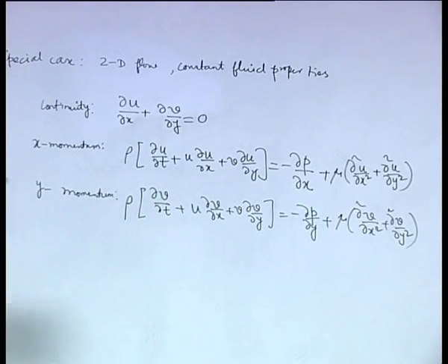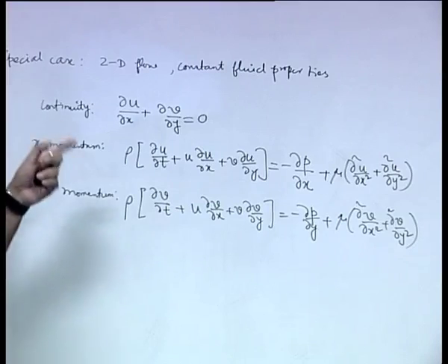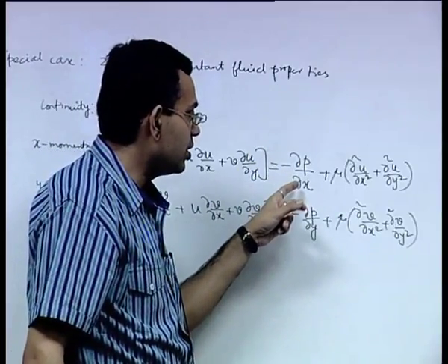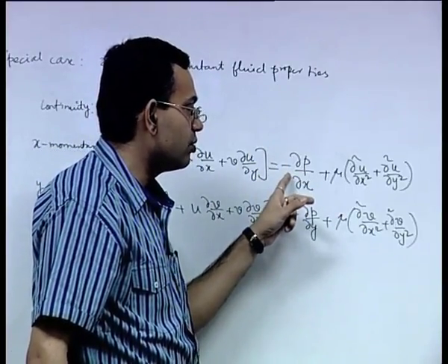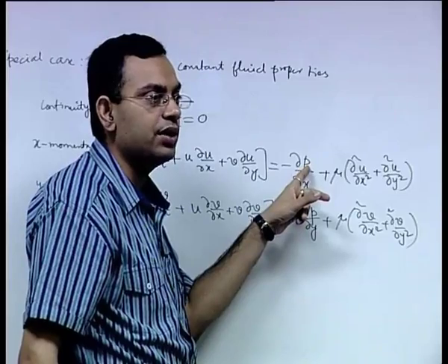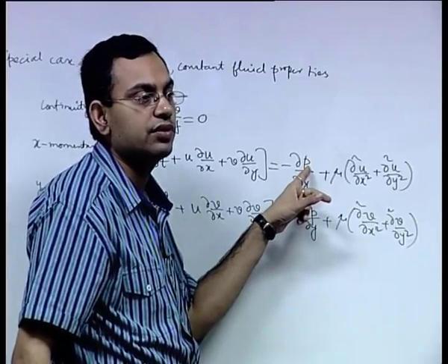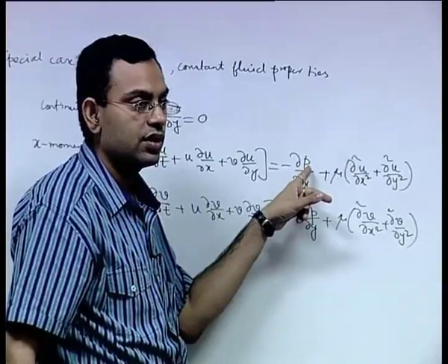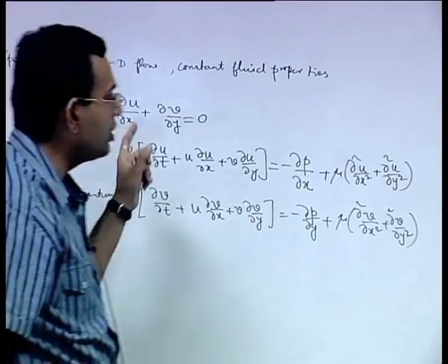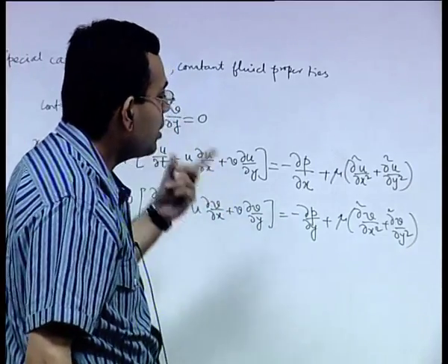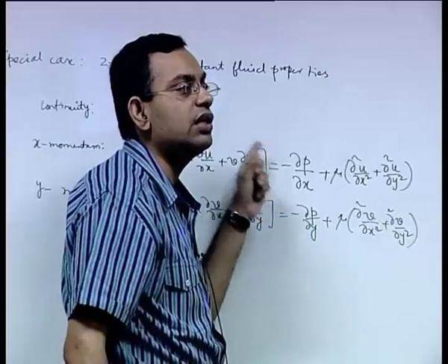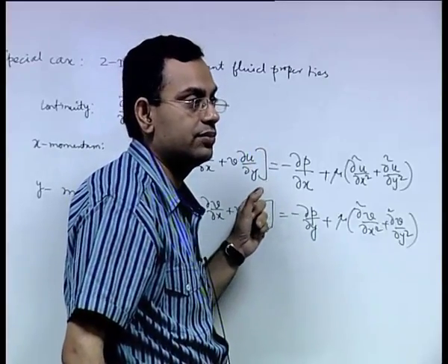So the issue is that yes, this is also a convection diffusion type of problem, but it has a source term which is a variable, that is the source term in which you have pressure as a variable but you do not have a separate governing equation for pressure. So you have a situation where you are having to deal with an undetermined variable as a source term where there is no explicit governing equation for that undetermined variable.